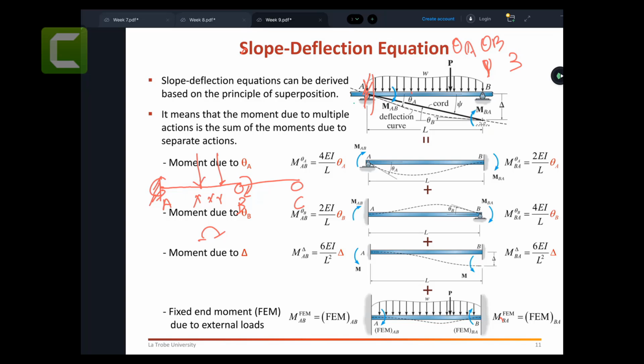So that is saying that if you have a load onto the members, let's say someone walking on the beams and someone standing in the middle of the beam and so on, then this method does not like it. It completely does not like it. It says that I don't like it. So we have a solution for that. What we do is calculate the fixed end moments. We have equations to calculate the fixed end moments to transfer all these forces to the respective joints. So that's how we solve these problems.